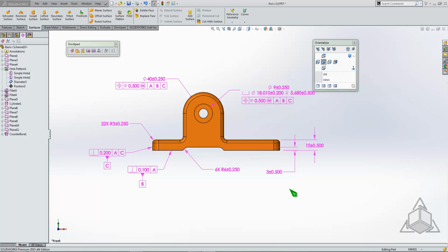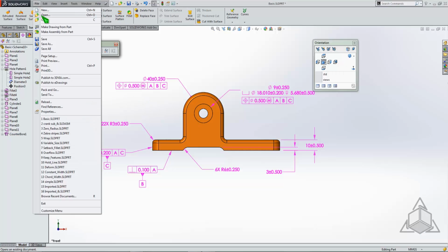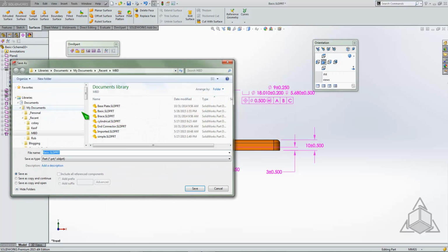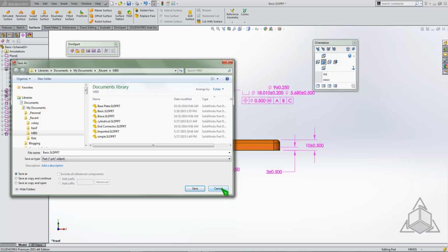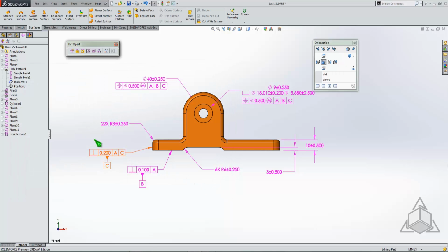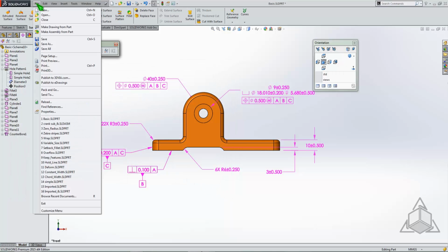So now that you have all of your geometric tolerances or your plus minus dimensions on the model, once everything looks good, your extension lines look nice, what are your options? What do you do with it at this point? Well, one thing you can do is, if you're working towards a paperless office, you can use the Save As command to save the part as an eDrawing. So that's one choice. Another choice is you could create a drawing just like you're used to.